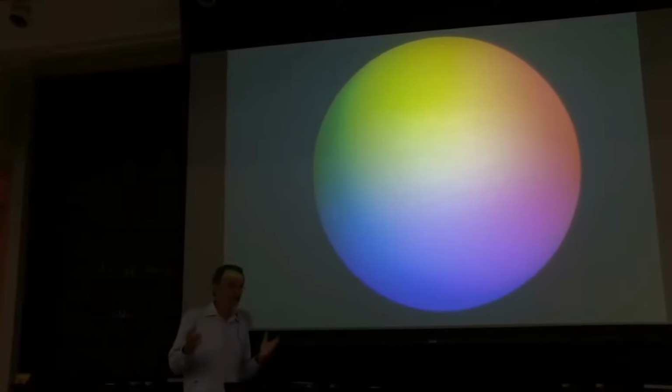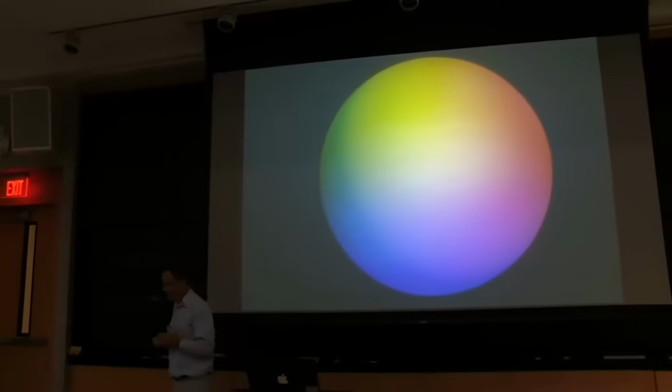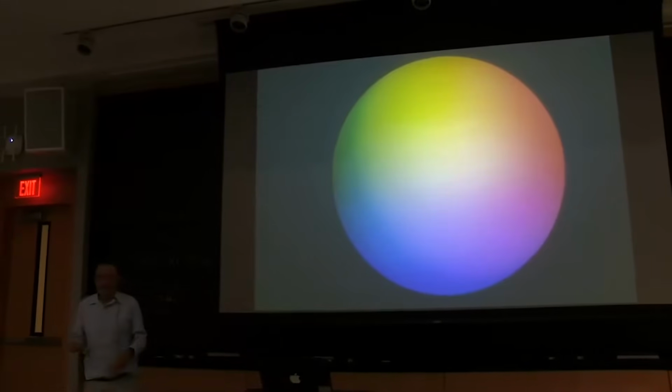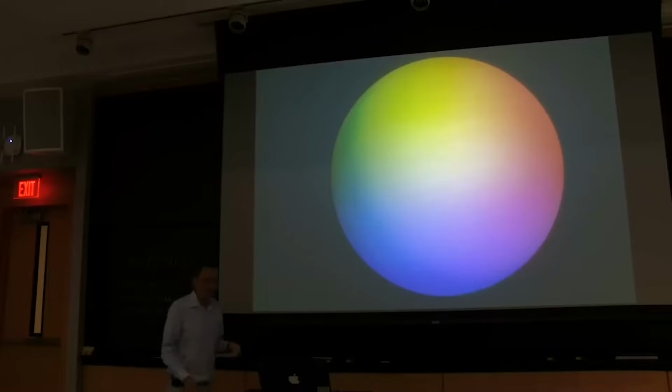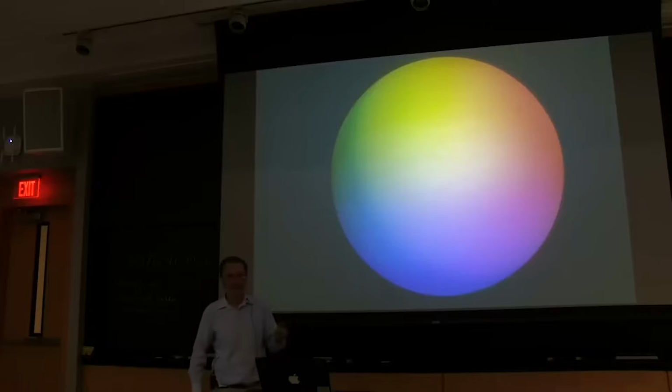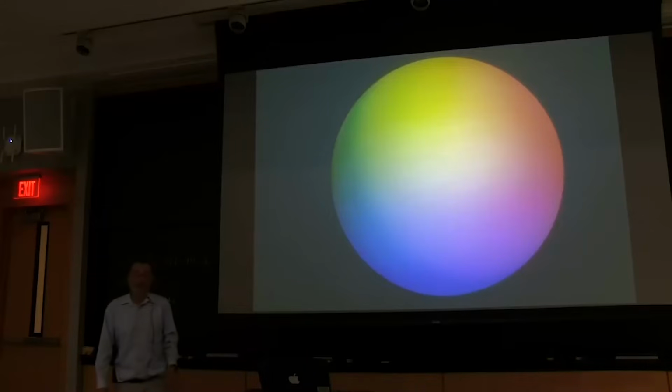Why worry about it? Well, images are noisy. So first of all, a lot of the images you're looking at, they're 8-bit images. That's 1 part in 256. You know, that's really crude quantization. And you can't even trust the bottom 1 or 2 bits of those. If you're lucky and you get raw images out of a fancy DSLR, you might have 10 bits or 12.